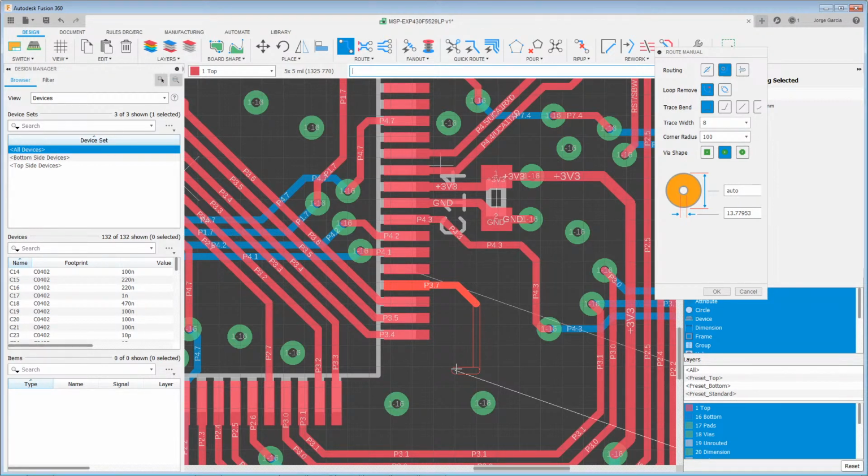Now, you don't have to always go over here to change the bend style, because that'll get old real fast. To change the bend style, you hold Control and you right click. And you'll see that you'll go through the various bend styles, and it'll just cycle. This can be helpful. Most of the time, you're going to want to stick to a 45 if you can.